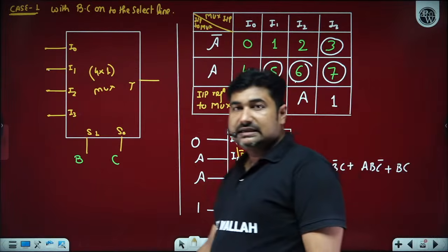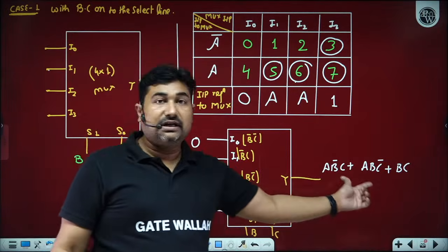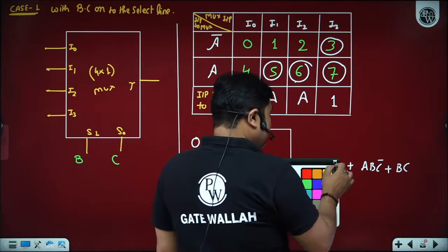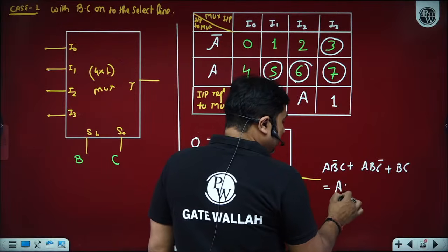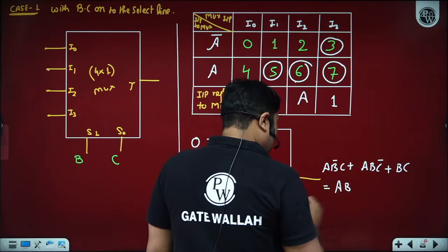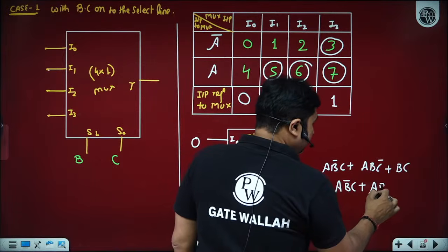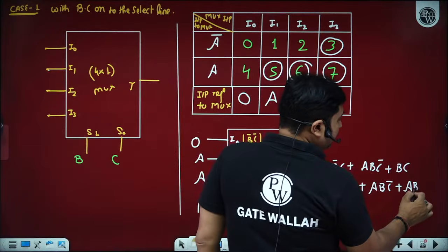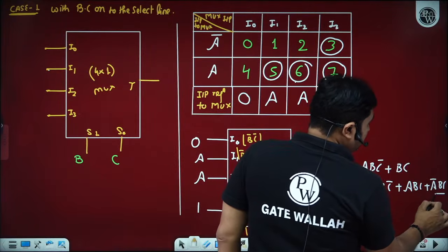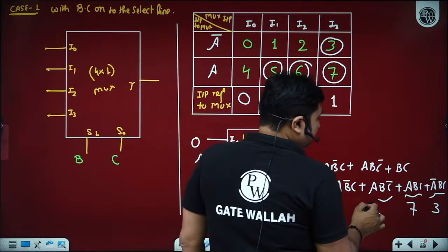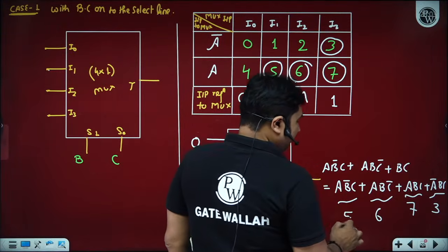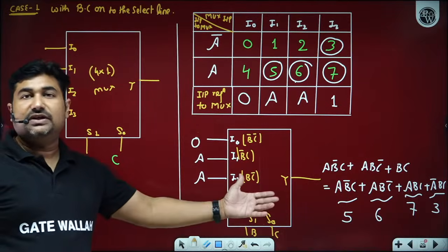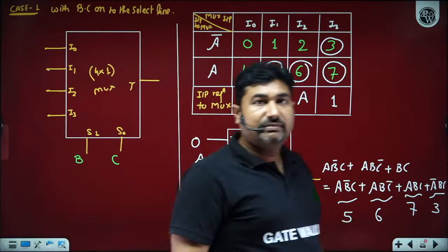So is this the desired function? The given function is not a canonical function. The multiplexer may give an intermediate expression. In order to identify the desired function, and to check what actual function is implemented, we need to write the canonical form. A is missing in BC, so we write A bar. So we will get ABC plus A bar BC. This is the binary of 3, binary of 7, binary of 6 and binary of 5. So the function implemented by the circuit is 3, 5, 6, 7. This is the same function we want to implement as a majority bit detector circuit.